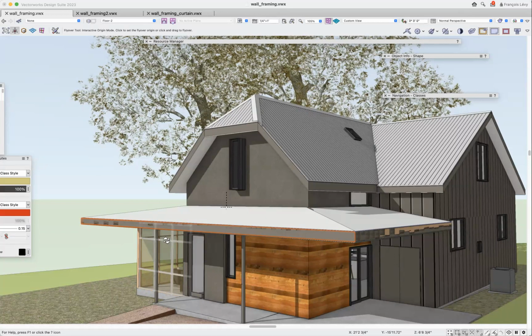And if you do add a fascia, the roof object has a fascia feature, which adds a fascia on top of what is essentially a subfascia, right? So if I were to build this roof today with the roof object rather than roof faces, I don't remember why I devolved it into roof faces, but I would probably add a fascia, and that's actually sort of realistic.